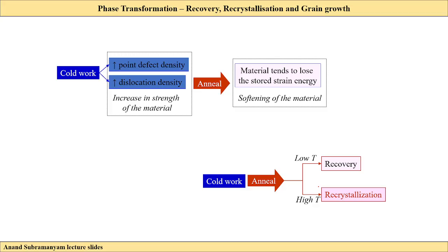So at a grain boundary there is a change in planar directions, right? For example, just like I have shown initially, what is the difference between grain 1 and grain 2 of the same type of phase? The orientation of atomic planes. So the dislocation has to change direction according to that atomic plane, right? Which happens when we give enough energy, when we deform the material to a certain level. But the dislocation will not move until we apply that amount of yield stress, right? That amount of energy is not given, that amount of deformation is not given.